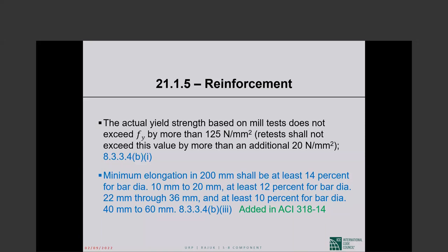So the higher shear force will cause shear failure preceding flexural failure, because we will not be correspondingly increasing the shear strength of the member. And shear failure is brittle, comes without warning. We absolutely do not want it. Okay. So that is supplemental requirement number 1. It is in 318-08. It is in BNBC 2020.